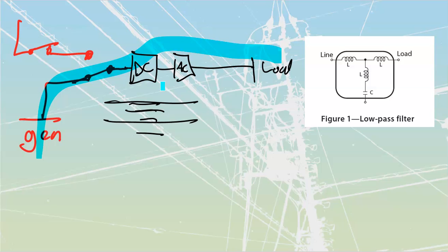And they're also going to choke back any sort of these spikes that are going to be coming through either to our motors or coming back from motors, etc. They're also completely passive. You don't have to engineer these things. You just place them in line with it. They don't do anything unless there's actually a problem on there. And then it's all just through the electromagnetic interface that they'll actually respond to these things. They are rated in impedances or %Zs.